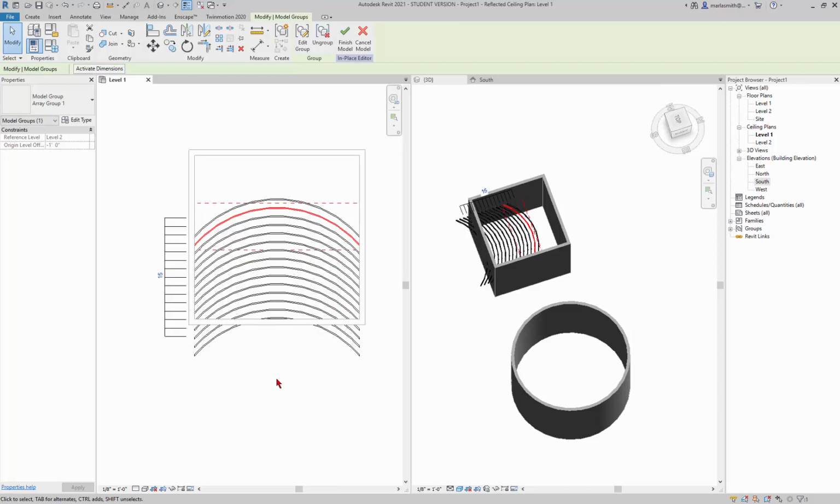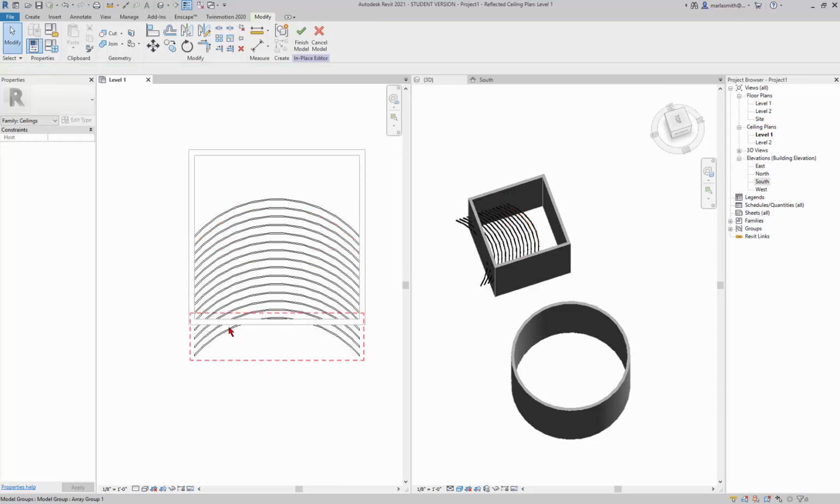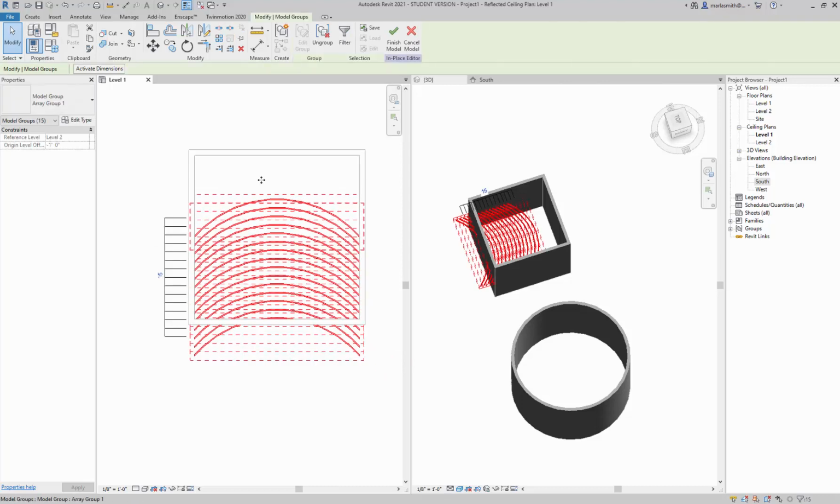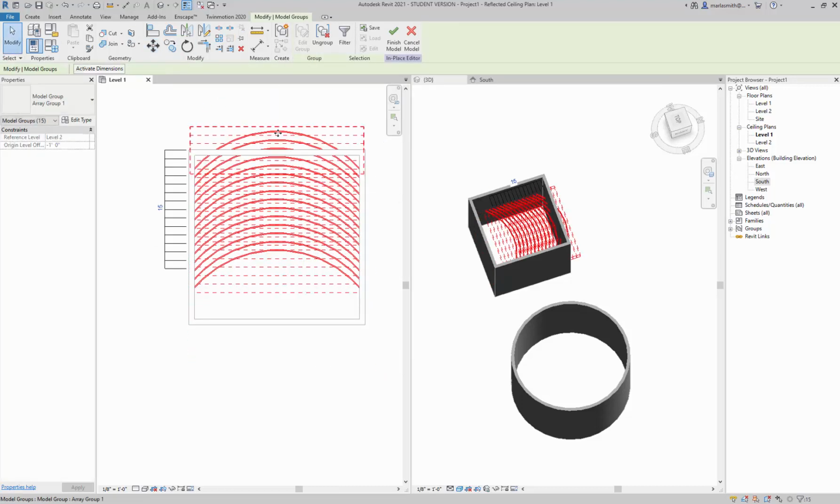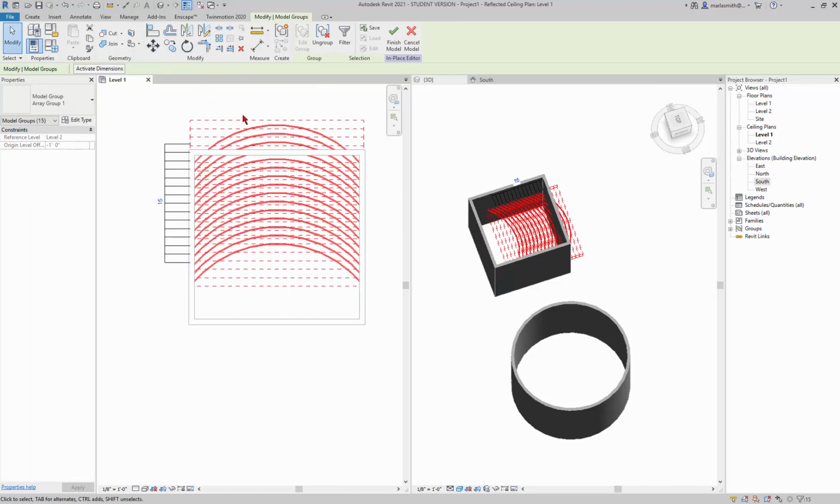Now, once you have this array, if you want it to trim at certain places, it becomes a little bit of a pain in the butt. So for example, if I come in and let me just move this array somewhere up here, maybe up a little bit more where we're kind of hitting it that way. And then let's go ahead and let's make it 20 again. Does that get us all the way? No, how about 25?